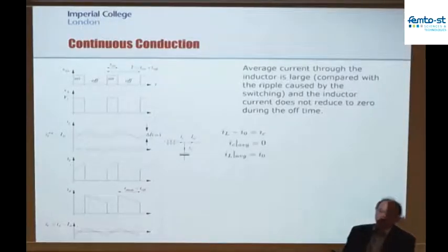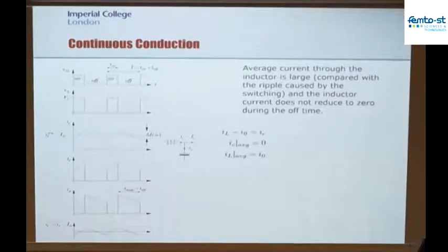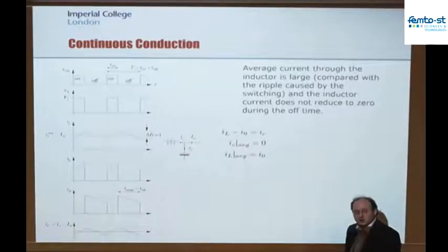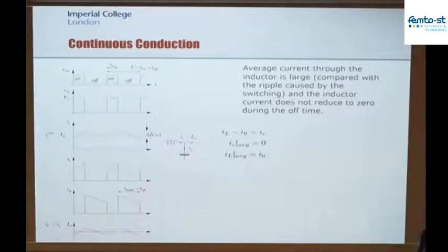And that's really inherent in processing electrical power. You're switching the way that current is flowing in the circuit from one loop to another loop so that you basically use that to either control a voltage by controlling how much of that current flows into a capacitor, or by controlling that current directly by measuring the current and changing the duty cycle and changing the path of that current to be able to control that current that's flowing in the inductor. So then the capacitor current is just the AC part of that inductor.